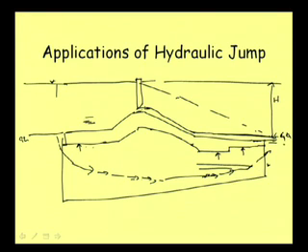For this part, suppose this is the uplift pressure, then from the upward side also the same pressure is there. So, for this portion of concrete we do not have any problem, we can provide nominal thickness here. Nominal thickness means for other considerations we need to design it, but as far as uplift pressure is concerned, this is not that significant.